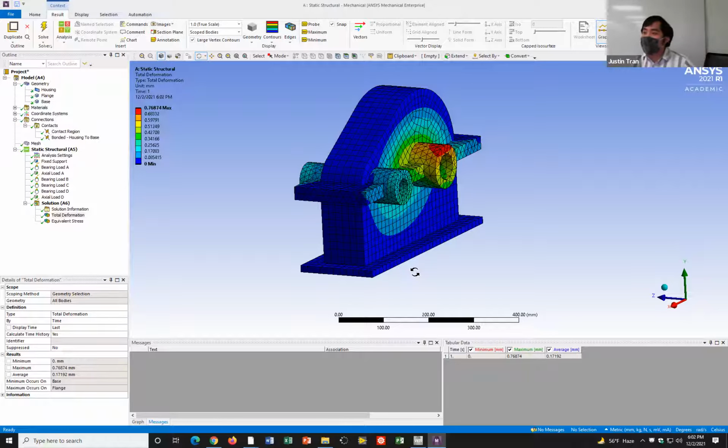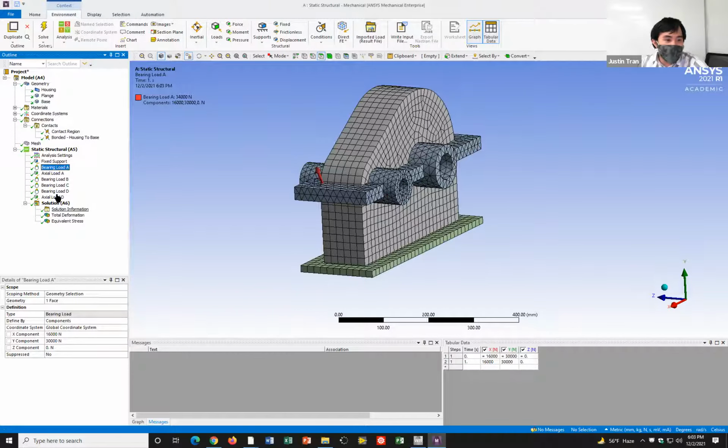What if it's the error of actual load? Instead of the error for bearing load having an actual component. If you have that error, then go to the bearing, each of your bearing loads, and just make sure the Z components are 0. For the Z components, you have to apply a separate force load for that.